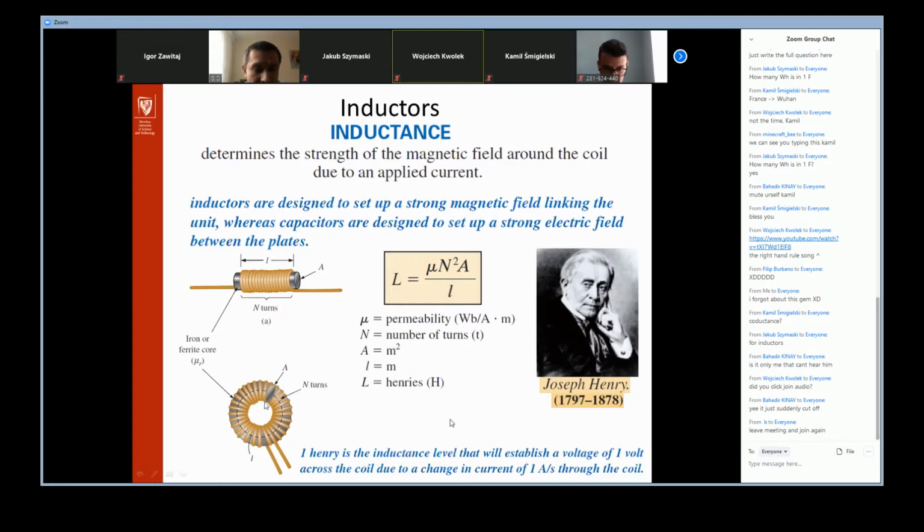As you see, for example here and here, the wires are touching together. So in fact, we will not have any turns, but a short circuit. So we don't have the inductor. You have to know that the wires should be isolated by a very thin film of insulator.